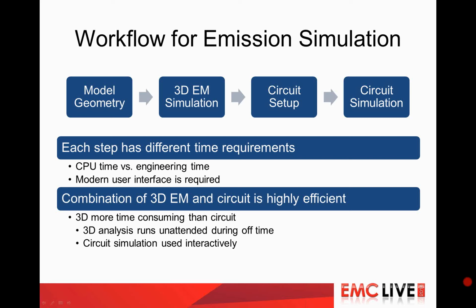When running the simulation with a 3D solver, there are different methods. I think most of you already heard about things like the FDTD method, the method of moments, the finite element method, and so on. There is a bunch of these methods, and each has certain advantages or disadvantages, and it strongly depends on the structure for which you use the method.